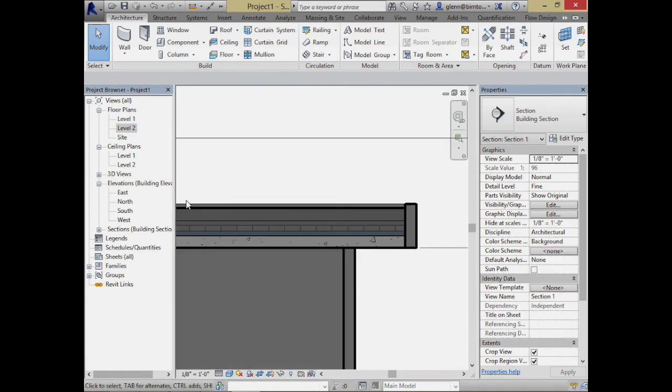Oh, no, we just have an issue of trying to keep the dirt up there. So yeah, you could actually try to taper it down, and some people would do that. You could make it structurally stable so it does have some sort of cleaning in here to make sure that it doesn't just wash away. So if you do structural analysis, does it change if you don't have the wall? Well, from a structural standpoint, most programs would just consider that a mass and not really think about the true properties of what it is.